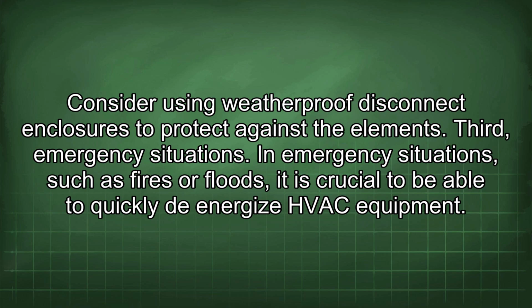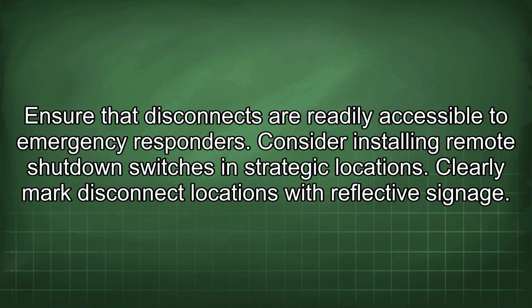Third, emergency situations. In emergency situations such as fires or floods, it is crucial to be able to quickly de-energize HVAC equipment. Ensure that disconnects are readily accessible to emergency responders.